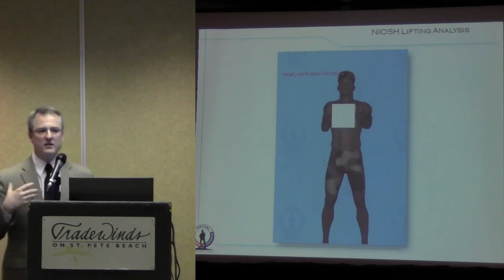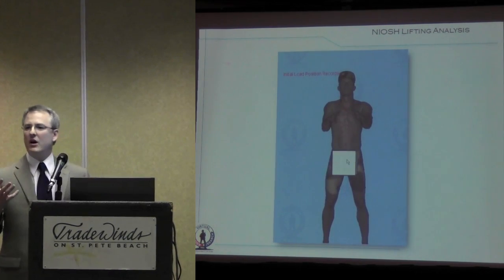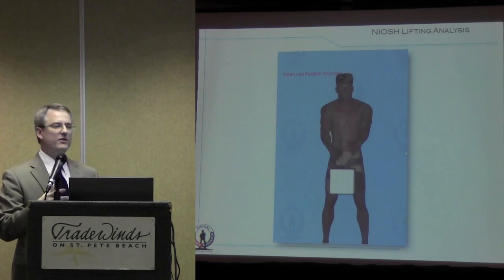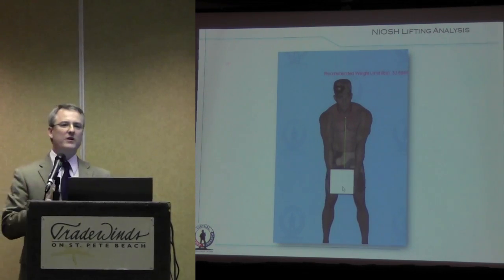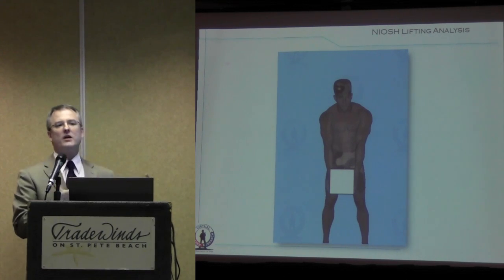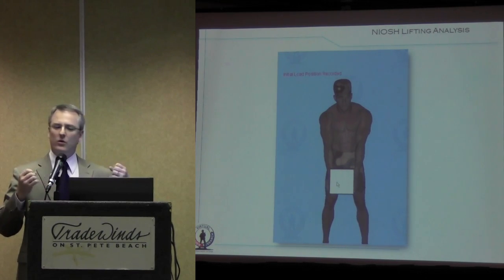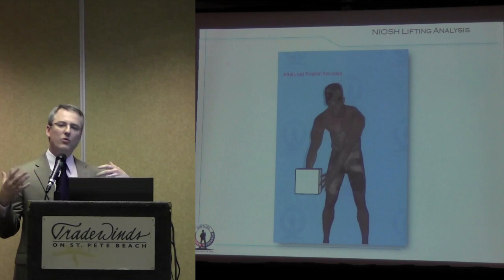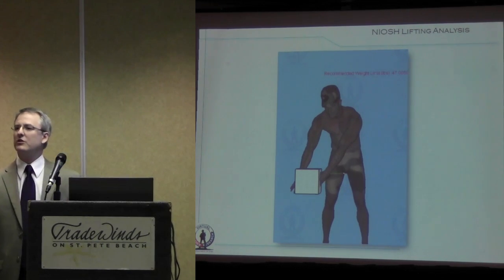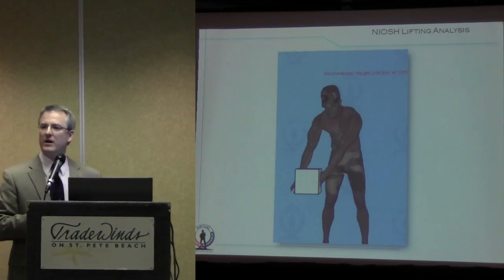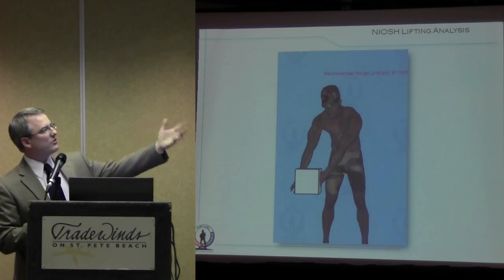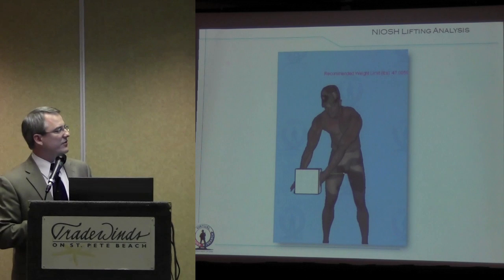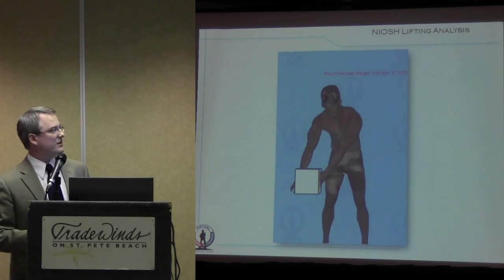In terms of the NIOSH lifting tables, this is another common tool that's now integrated within Santos to position a box, say at an initial position, a final position, and then what is the recommended weight, or excuse me, what percent of the population could conduct that task given the weight of the box and the distance it's going to travel. It also will give you the recommended weight for that task if it's not specified initially.